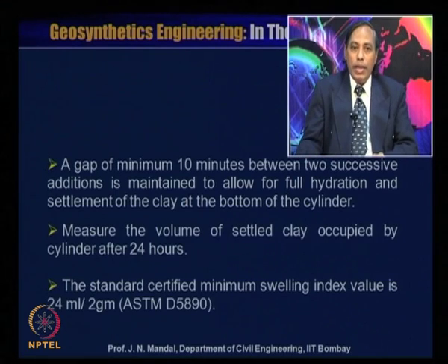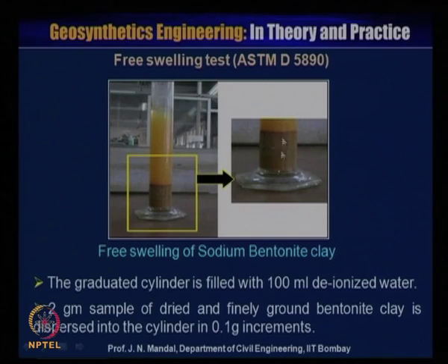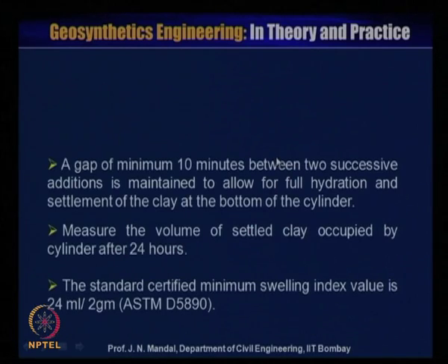You can see that after the 24 hours you can measure the extension here. So you can measure that it will be 24. It should satisfy the minimum swelling index criteria. If it satisfies, then it is okay.